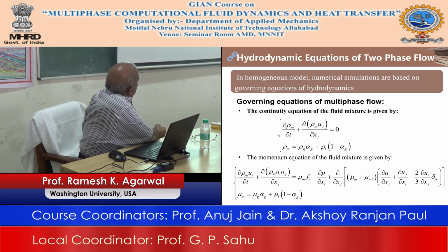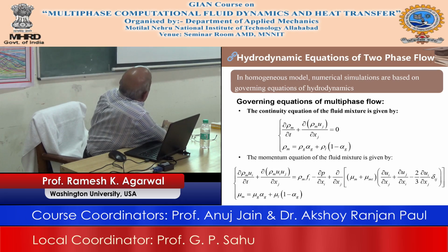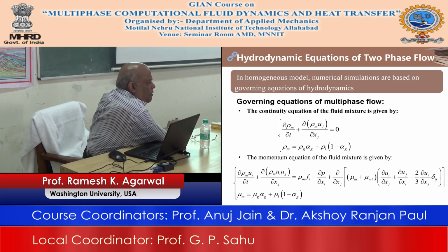So what you have then is this equation, and this is the governing equation. This is the continuity equation, and this is the mixture, and the mixture has two parts, the gas and the liquid. So, standard mixture: this is the conservation of mass, which we have seen before, and this is the conservation of momentum. In this model there is no surface tension at all, because we are not dealing with individual bubbles. It's a simple application of Fluent.